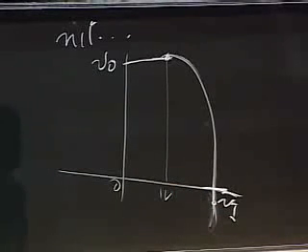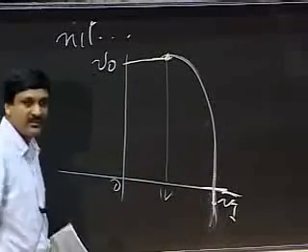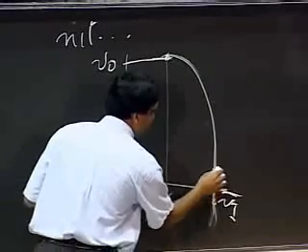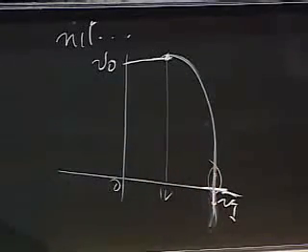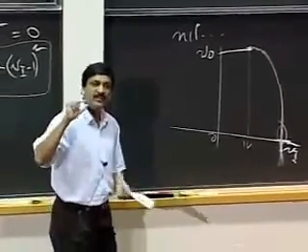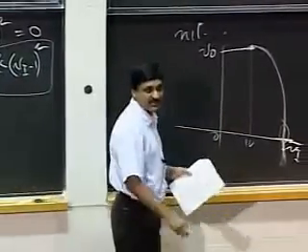So mathematically, this curve says that the device has begun to supply power. It turns out in our practical device, it's a passive device, so it cannot go here. What happens is that somewhere along here, the model breaks down. The equation I've shown you for the current source, here we go. This model breaks down. When V0 becomes very small, the model breaks down and it no longer behaves like a current source.